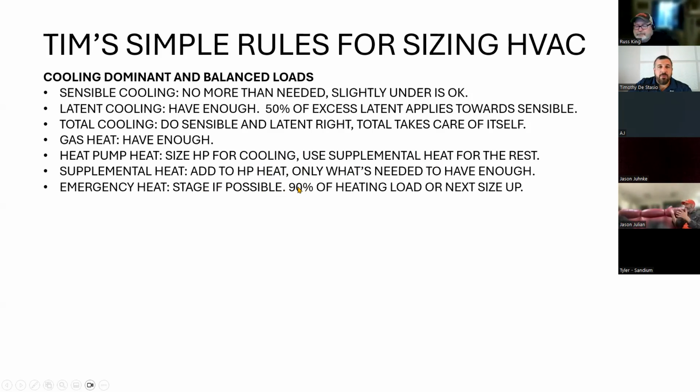We don't have to meet 100% of our heating load. We can get close to it, or maybe the next size up if we don't think it's enough. But again, don't overkill the customer on emergency heat either. And offer dehumidification, because newer units don't dehumidify that well. And sometimes we're just going to have a shortfall that we have to deal with a dehumidifier.